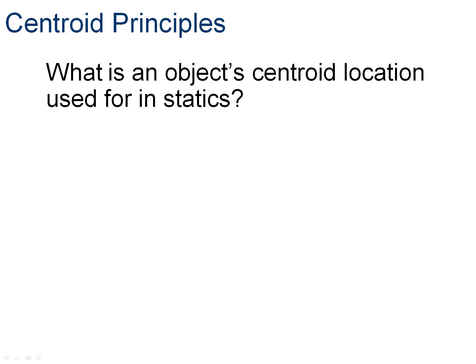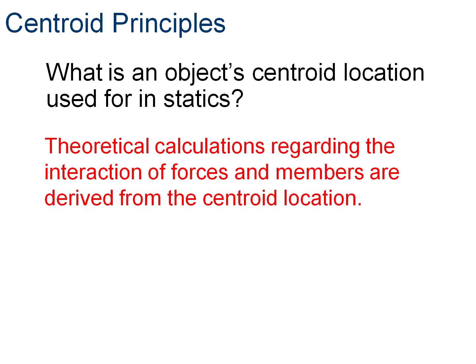So what do we use it for in statics? Why do we care about the centroid? The reason we care about the centroid here is we use this for some theoretical calculations, talking about how forces interact within a member. And a lot of that is derived from the centroid location. We'll see that at the very end of this presentation. If we put an object in a bending moment, what we will see is along the centroid is the plane, the neutral plane, and that's where the element goes from tension to compression.